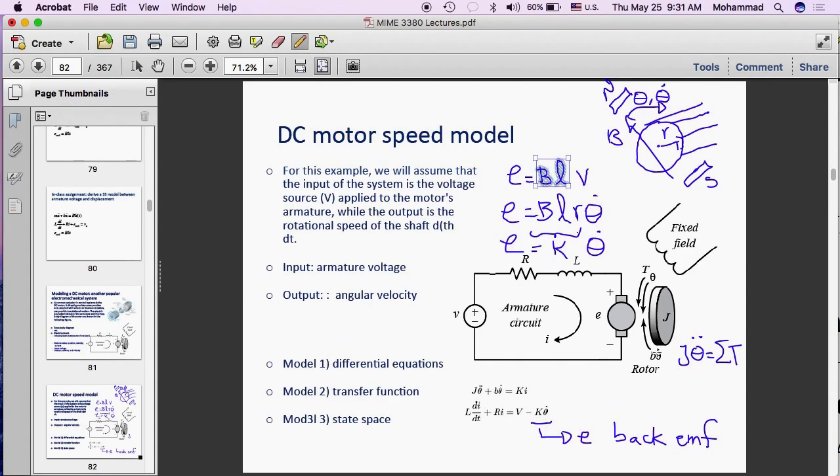So if you look at the law of motors, it basically says F, the force generated, is equal to B, strength of magnetic field, times L, times I, the strength of current passing through the conductor, through the wire. Now, in the case of a coil winding around the cylinder, like what we have in a DC motor, we are not looking for the linear force.